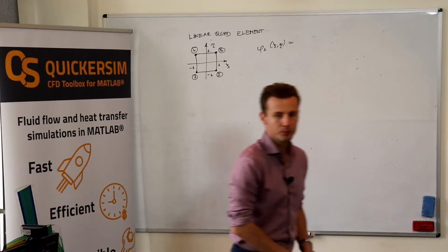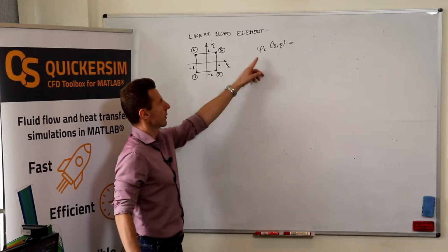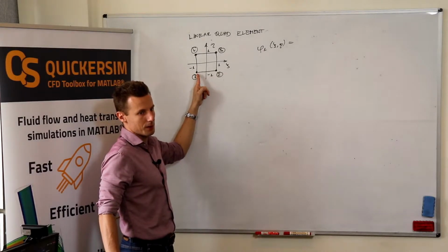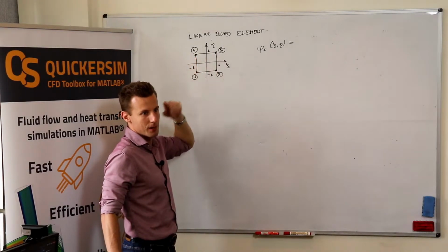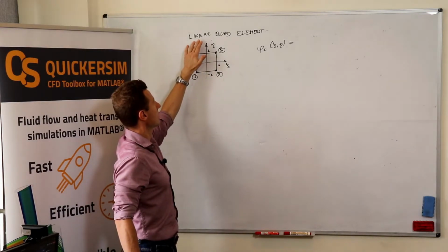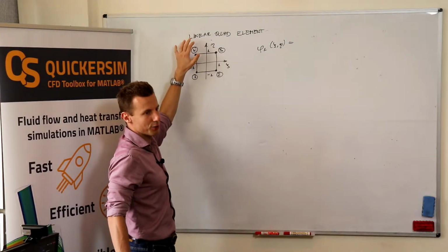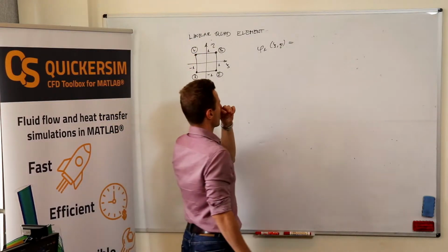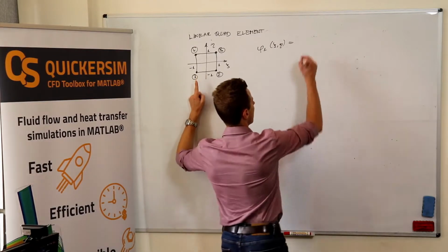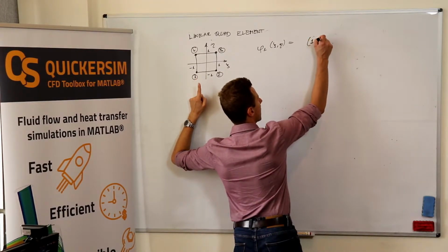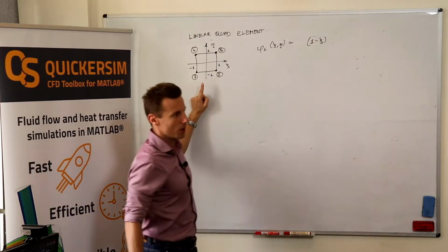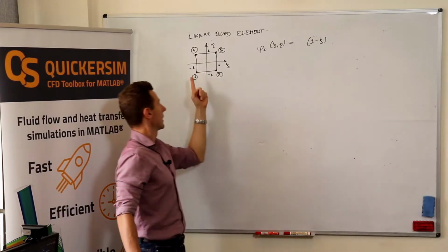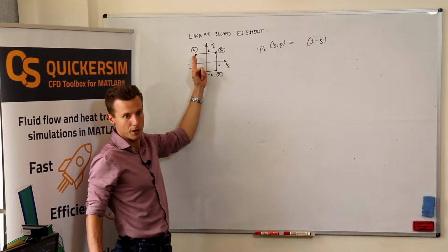What do we need to have? We need to have a shape function for the first node that is exactly 1 here and is 0 everywhere else. And we want to have a linear element. Actually, it's not really linear, it's bilinear. So let's take something like that. 1 minus psi looks like something that will give non-zero here, and it will give 0 here.